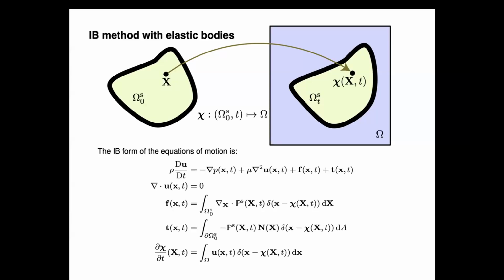We have one momentum equation that we're going to use for everything. In the fluid region, it's the fluid momentum. In the solid region, it's the solid momentum. These terms are where the fluid-like stresses are showing up, and they're distributed throughout the entire computational domain. And so in particular, there are these fluid-like stresses that are in the solid region. And then there are additional elastic forces that show up just in the solid region.